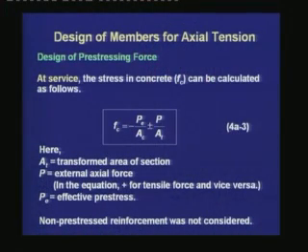Next, we are moving on to the analysis of stresses for service loads. At service, the stress in concrete can be calculated as follows. Fc is equal to minus Pe by Sc, which is the effect of the prestressing in the concrete, and plus minus P divided by At. Here At is the transformed area of section, P is the external axial force. In the equation, plus is used for tensile force and minus is used for compressive force.